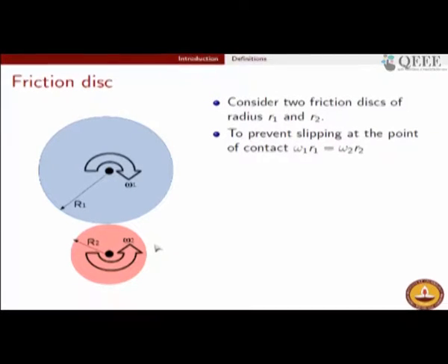If you have gained speed by a factor of 2, then you would have to lose torque by a factor of 2 again. So that is a rule which you cannot play with. The product of the speed and torque has to remain constant, because the total energy or power has to remain constant.